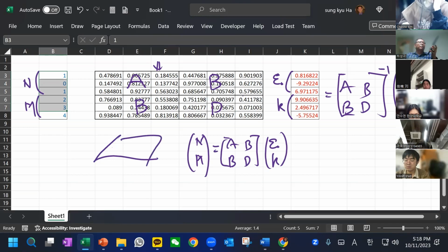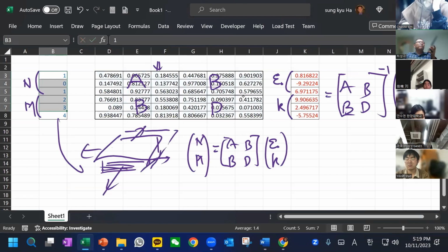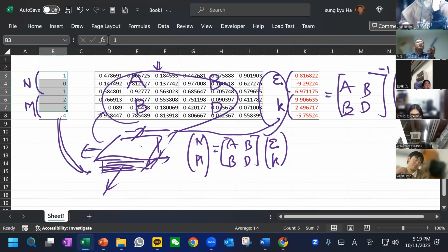And here we have many plies, and we're going to have a load N1, and this is the load. How much will it deform? This deformation will be here. So the whole layup sequence will give us this, and then if we know the load, we can calculate the strain. This is classical laminate theory.